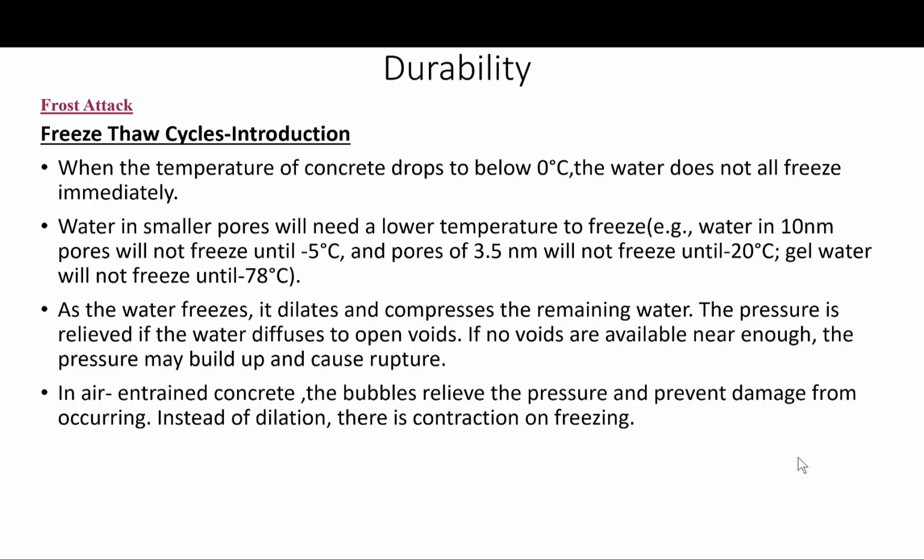As we know, porous materials containing moisture are susceptible to damage under repeated cycles of freezing and thawing, otherwise referred to as frost attack. The hardened cement paste, which has a high porosity, is particularly susceptible to such conditions, and concrete may be destroyed in a single winter in the northern climates, like in the northern US and Canada.